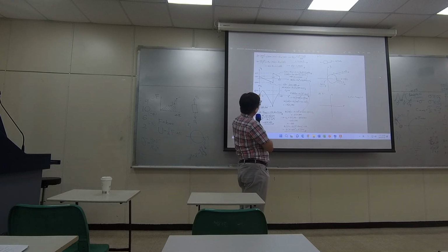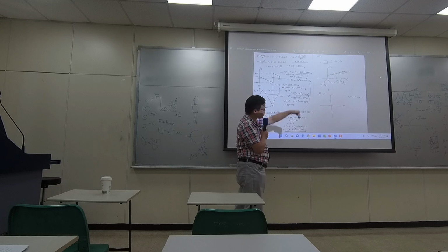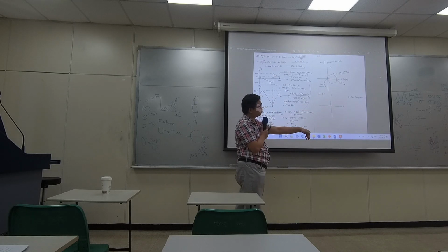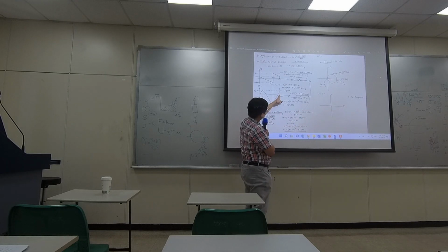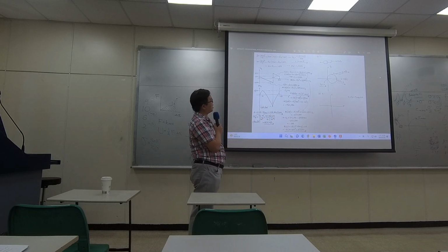Because there's no force on the left edge of the bearing, the moment should be zero right here. However, on the very right edge, there's a force at the right edge, so there's moment. So it's common if you see some moment at the very right edge.